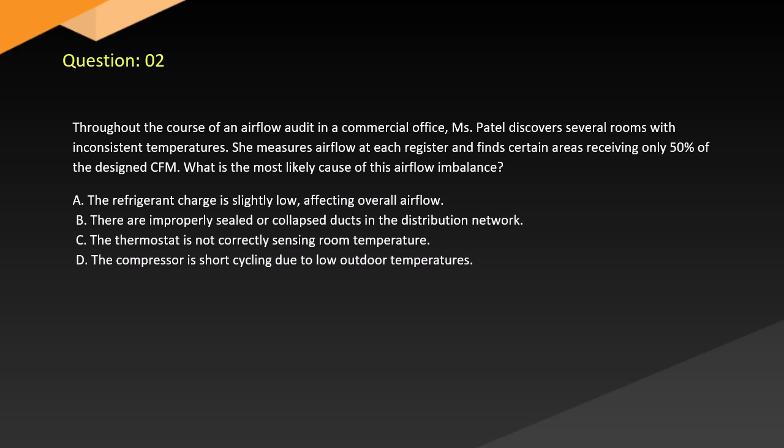A. The refrigerant charge is slightly low, affecting overall airflow. B. There are improperly sealed or collapsed ducts in the distribution network. C. The thermostat is not correctly sensing room temperature. D. The compressor is short cycling due to low outdoor temperatures.